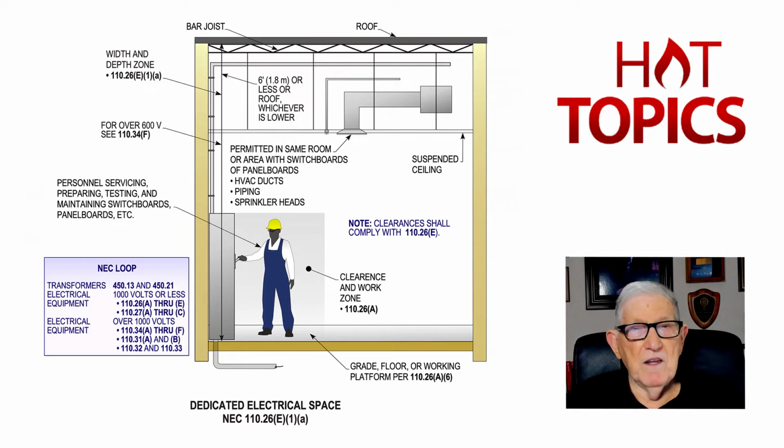And then notice, as an installer, electrician, you want to make sure that there's not a wall behind that person's back. Remember, condition 1, insulated wall. Condition 2, grounded wall. Condition 3, equipment opposite equipment.